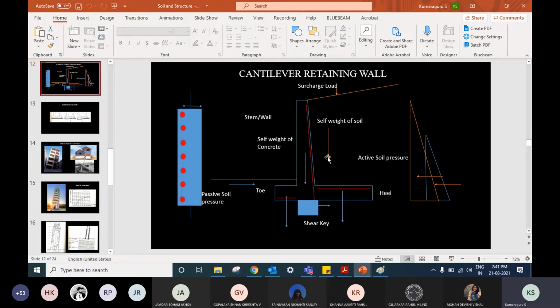Okay, that is one. Second thing is, this is the bending moment calculation. There's something called shear force, right? What is the shear that is coming at each place? What is the maximum shear? Is our capacity at that particular zone meeting the shear or not? So you figure out these reinforcements to be put, including vertical and horizontal and all those detailing.